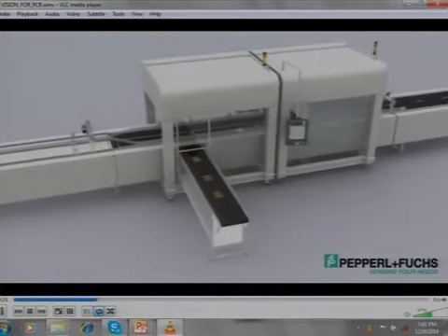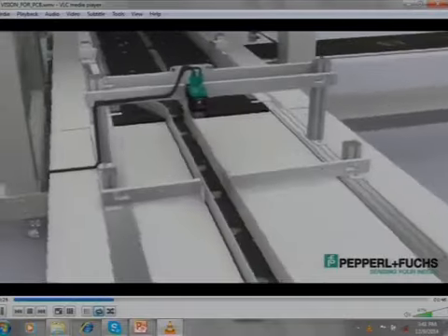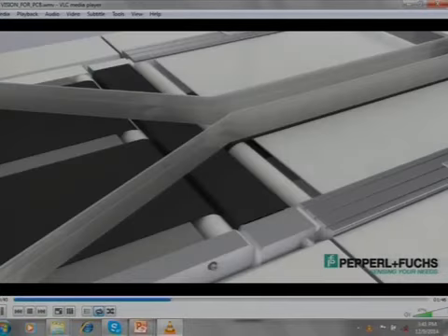So, this is just an example of a video which shows a PCB machine having a number of PCBs mounted on it. Now, this is a PCB which is supposed to be checked for its pattern. If the PCB is broken or damaged, the image comparison will show it. We are not getting the same result, the pixel values are changing. So, based on that it is rejected from the line.